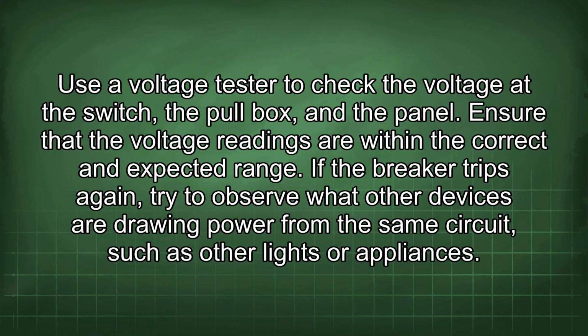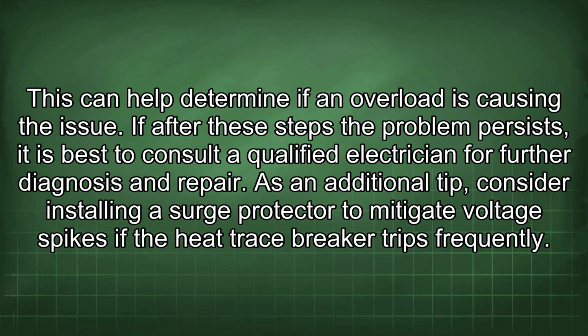If the breaker trips again, try to observe what other devices are drawing power from the same circuit, such as other lights or appliances. This can help determine if an overload is causing the issue. If after these steps the problem persists, it is best to consult a qualified electrician for further diagnosis and repair.